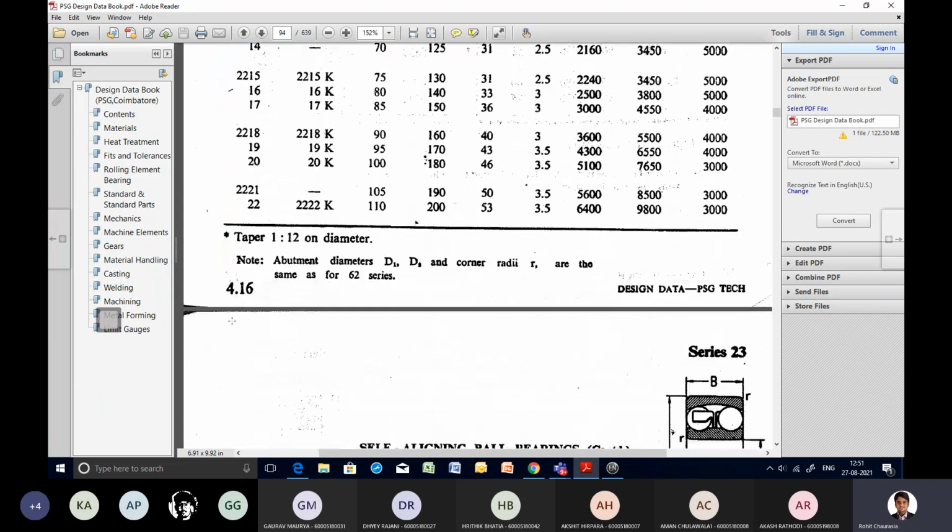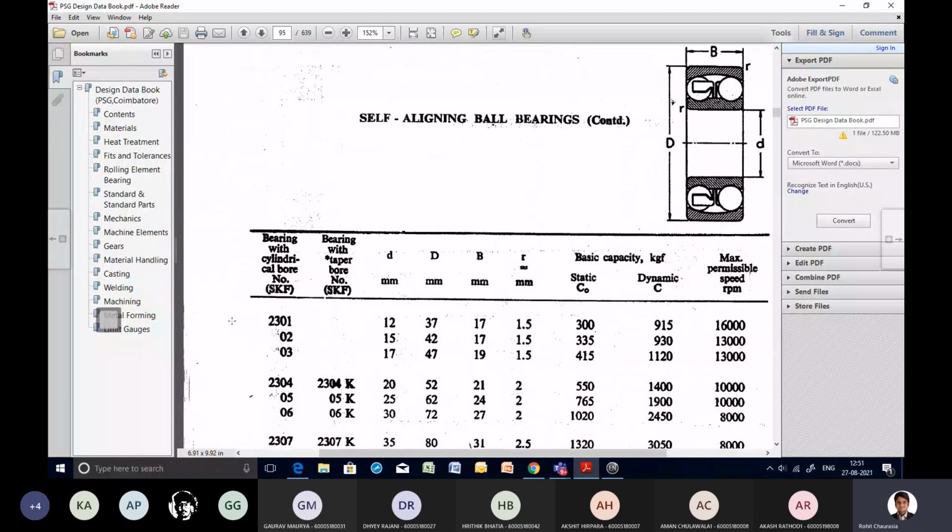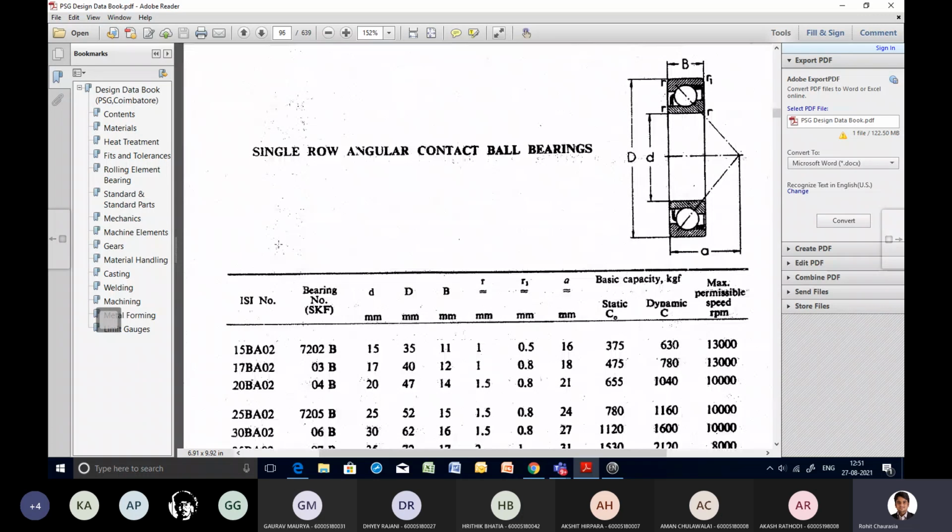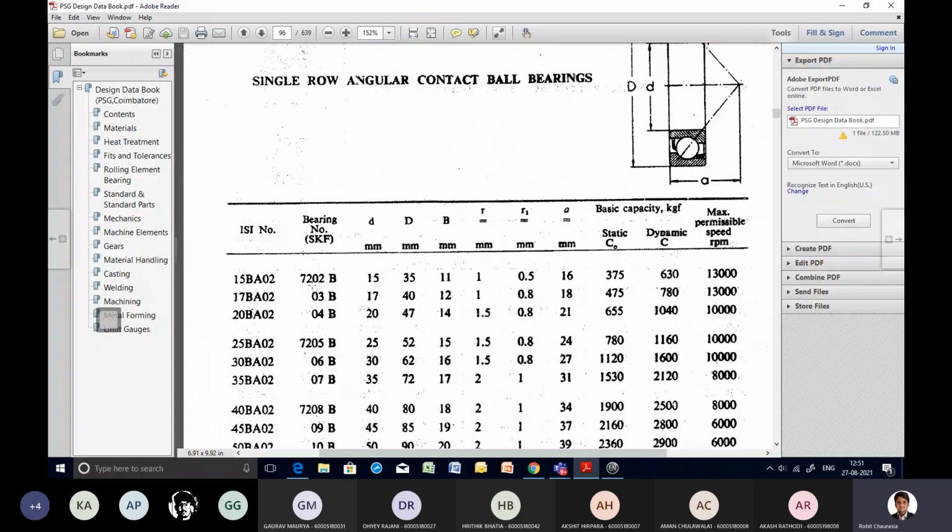So here from this table you can refer to the bearing number. यह यहाँ पे मेरा क्या represent कर रहा है, 3 is nothing but the medium service. Similarly, you can find out the last 2 digits, multiply by 5, you can get the shaft diameter. हमको यहाँ से चालू करना है, हमेशा 4 वाले से we can apply. But this 2 is nothing but the type of service. This 7 is nothing but the number for the single row angular contact bearing. So basically always we have 4 digits. तो यहाँ से last 2 multiplied by 5 will get the shaft diameter.